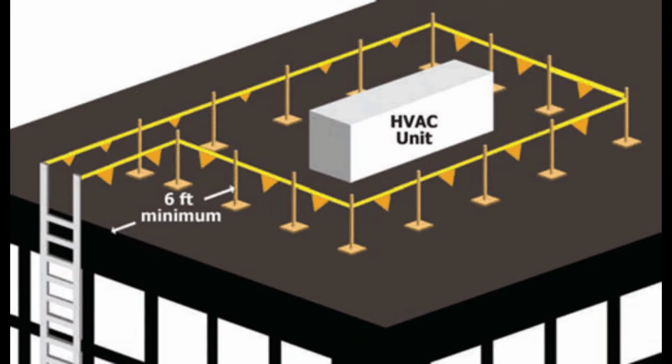When used to control access to areas where overhand bricklaying and related work are taking place, the controlled access zone shall be defined by a control line erected not less than 10 feet (3.1 meters) and no more than 15 feet (4.5 meters) from the working edge. The control line shall extend for a distance sufficient for the controlled access zone to enclose all employees performing overhand bricklaying and related work at the working edge and shall be approximately parallel to the working edge.